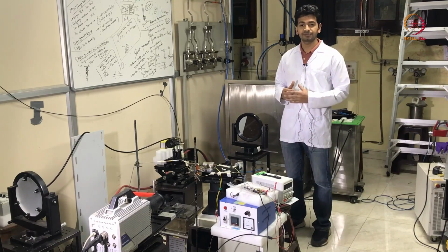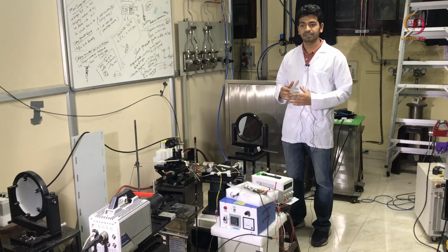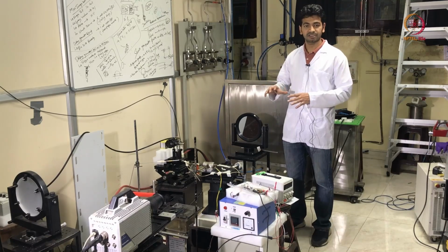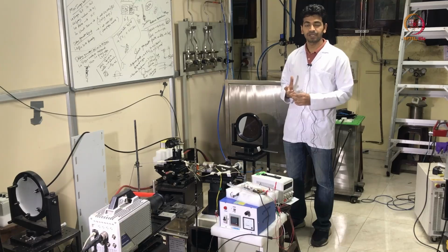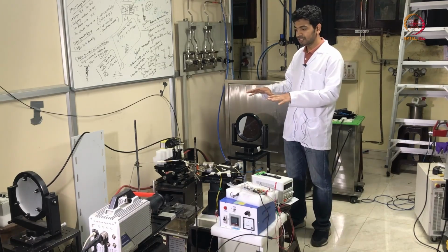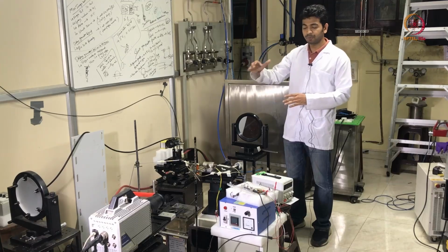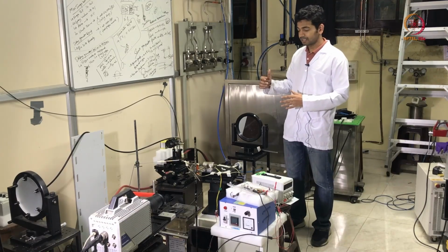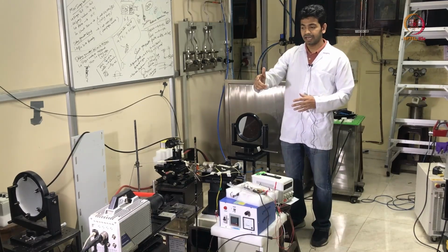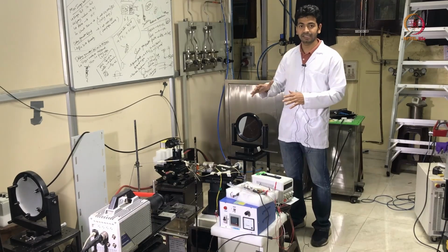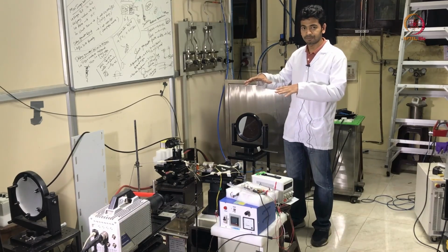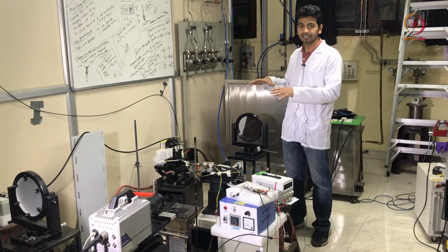There are various versions in which people do setup for Schlieren imaging. Either it can be using one mirror or two mirrors, and they are arranged in different fashions. The one that we have here is a setup with two parabolic mirrors, a light source and a camera, and all these components are arranged in a fashion that looks like the letter Z when viewed from the top. So it's a two parabolic mirror Z type setup.